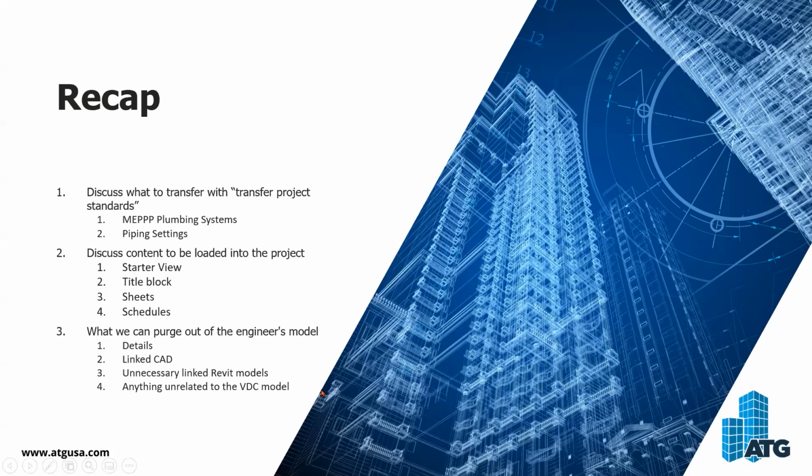Any unnecessary linked Revit models. So in some cases, architects will have 4 or 5 different design option models in there, and instead of using design options, they create new Revit models. Well, that's something that we can clear off as well, and that will help provide some better performance also.